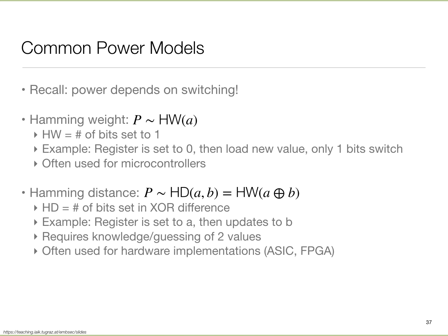It's called DCVSL logic. It's twice as costly because it's twice the number of transistors, but basically, to first order, it consumes the same amount of power and the same amount of delay, irrespective of what the input is. So at the logic level you can also address these things. All these levels you can address, right? You can add capacitors. I'm not quite sure how we'll get your noise idea to work, but in principle it seems like a reasonable approach: I shoot noise outside and make myself immune to it. Maybe we can get it to work.